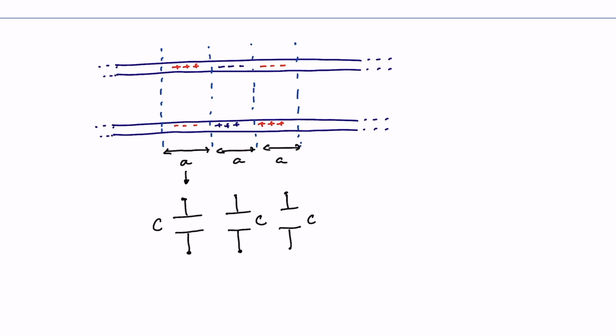But there is also the issue of current flowing in the structure, and these currents generate a magnetic field, and the magnetic field again creates electric fields and so on. All these features can be incorporated into the model by joining these nodes by an effective inductance, say L. Similarly here you are going to have an effective inductance L. Why am I saying effective inductance?